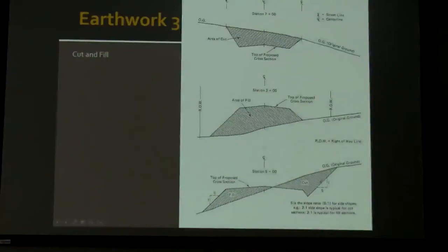Down here we have a combination cut and fill project. We'll be filling an area here, and we'll be cutting an area. What we're doing here is filling one side, so that one side of the pavement, maybe northbound, would be filled, and this would be our center line. Then we have our slope for the pavement, and then the center line, and then we'll come back, and in order to achieve the same slope, we'd have a cut project. And again, as we leave off the shoulder, we'll have a greater slope for our runoff purposes.